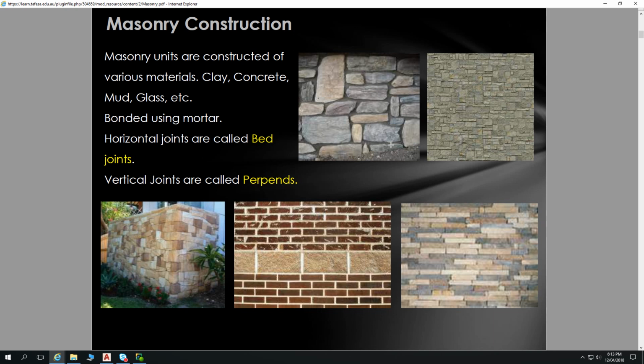Some terminology around that. All of our horizontal joints, it's very easy to see with our brickwork. These are our bed joints because they provide the bedding. So all the mortar that goes underneath the bricks, that is our bedding. All the mortar joints in between the bricks, they're our perpends because they're perpendicular to the bedding joints. With stonework it gets a little bit of a grey area. Some of those, are they bed joints or perpends? So it's very clear and easy to see with our brickwork.